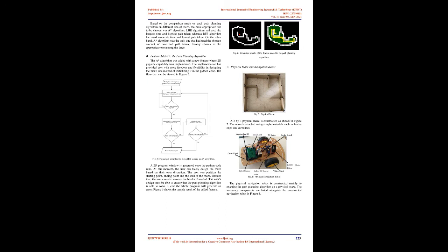This algorithm operates by taking precedence to the left-hand side in the maze [16]. Therefore, when the algorithm is placed into the maze, it will run accordingly by sticking to the left-hand side at all times. As the algorithm reaches an intersection, the left side will take priority first. If the left side is open, the algorithm will turn left then move forward. Otherwise, it will check to see whether it can move forward or not. If there is no forward option, the final resort is by turning right [17].